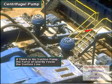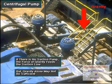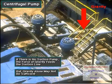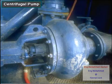If the system does not use a charging pump, the force of gravity alone feeds the pump's suction line. Sometimes, gravity cannot keep the pump's intake completely full of mud. The pump pistons suck in the mud so fast that gravity cannot keep the suction line full of mud. The crew also uses a centrifugal pump to mix some mud components.